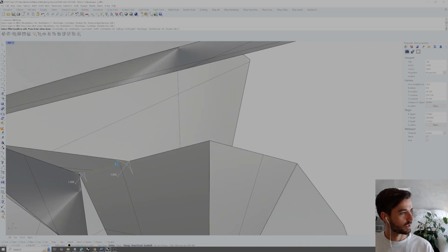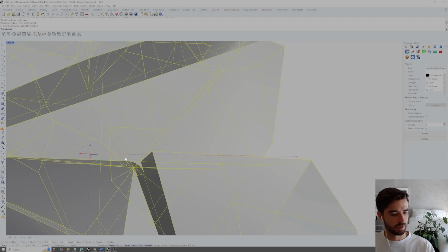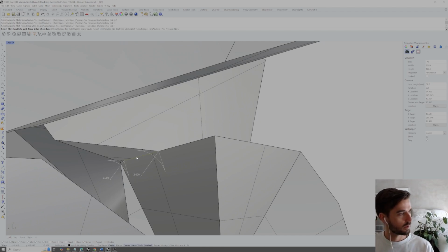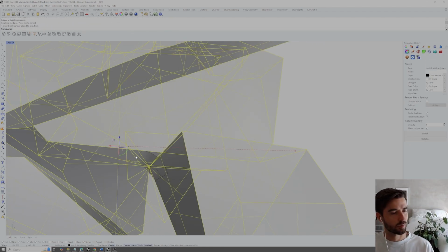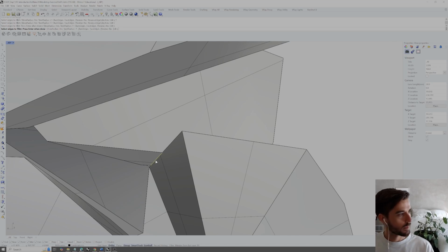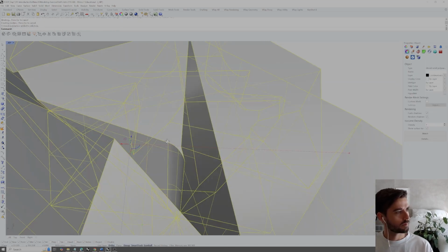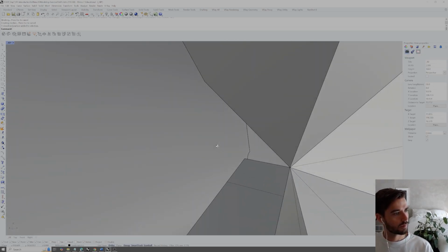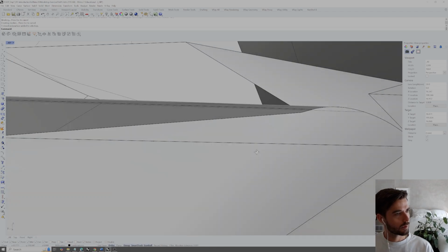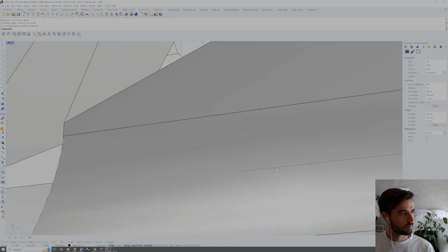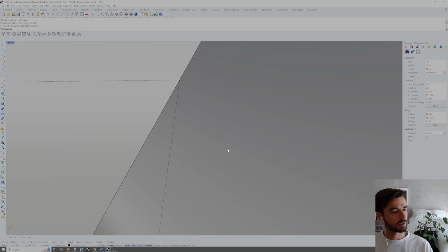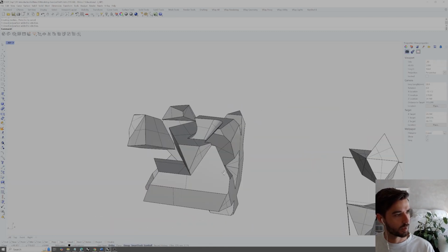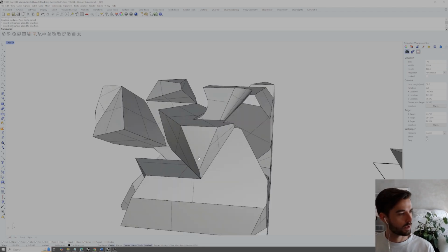Let me try adding a fillet just there. Let's see. Okay, so that does stay, so maybe we can actually get a larger fillet in here, which appears as a bracing. Okay, it looks like that's actually closed for us as well, which is great. It says that it's a closed solid polysurface, but you do want to double check those intersections.